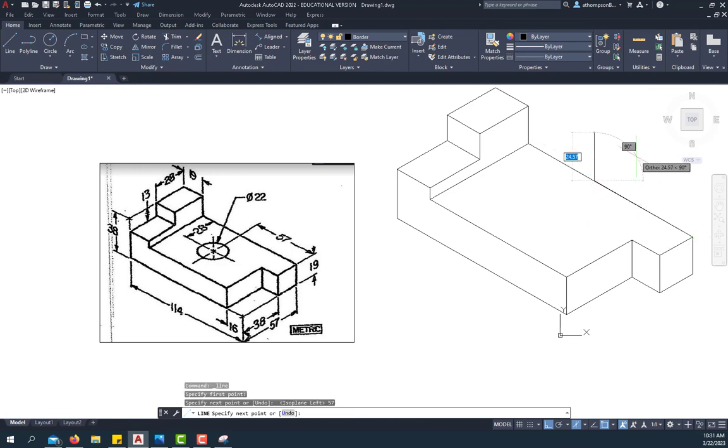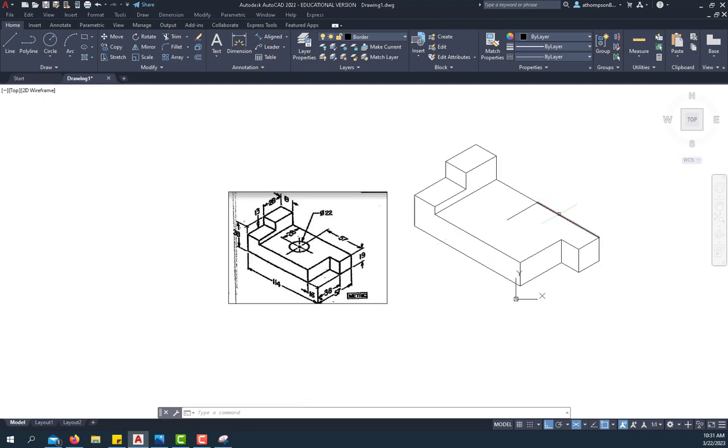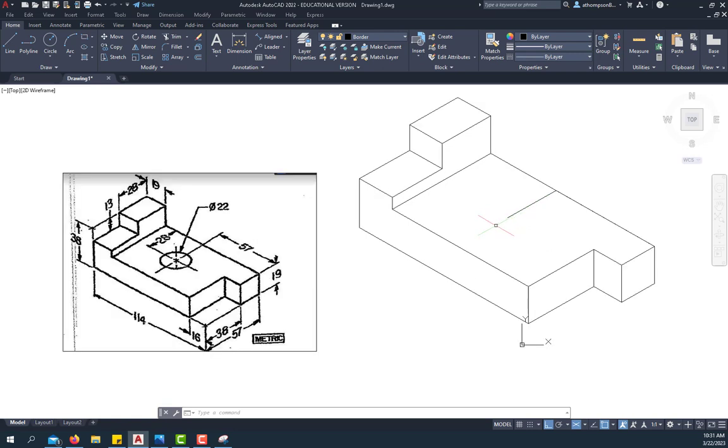That puts me here. I'm going to hit F5 again so I can bring it towards me, and I'm going to type in 28, enter. So it's just like putting those measurement marks on your paper when you measure along the line. And so this little spot here is the center of that circle.